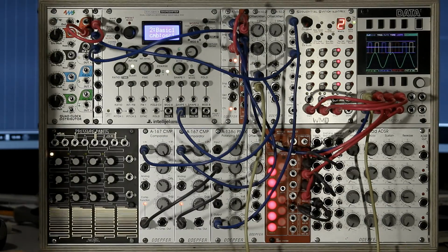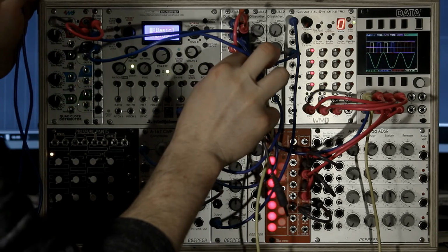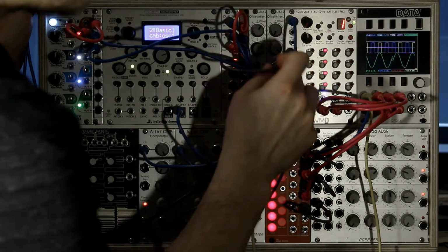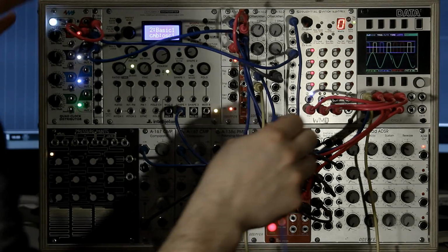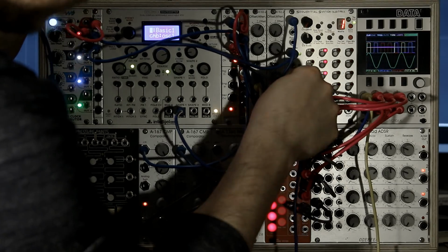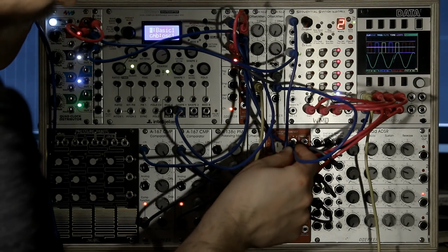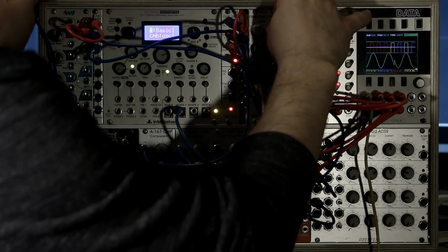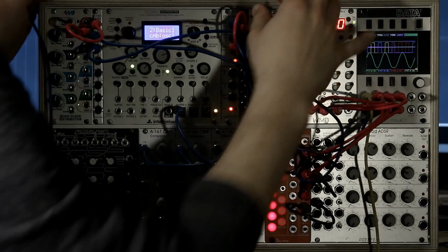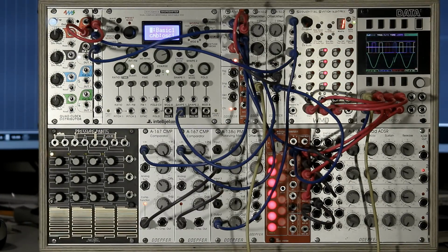Let's get the LFO signal that will be used to create pitch values. I want some additional control over that signal, so I am passing it through an offset and attenuator module. This will enable me to offset and modify the range of pitch values independently of the main comparator signal. So the comparators will always stay very accurate in full range, while I could be, for example, generating melodies within 1 octave or in the range of 1 volt.